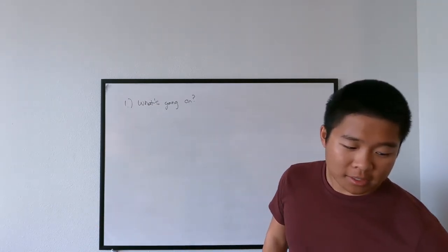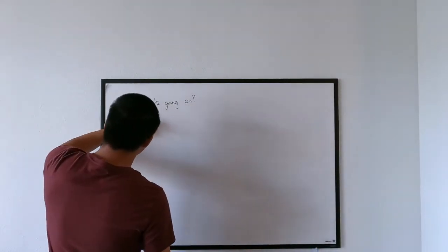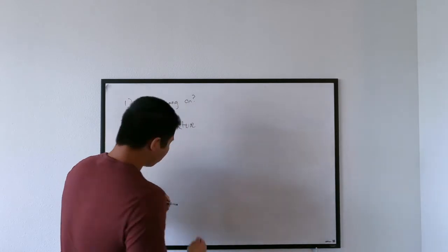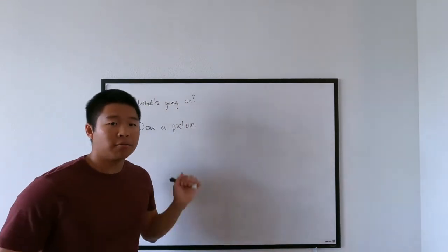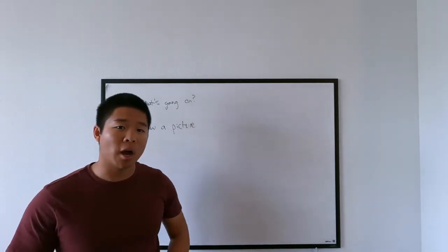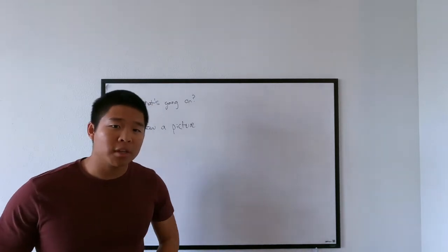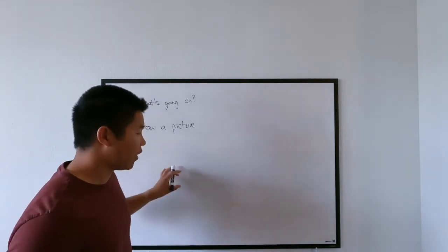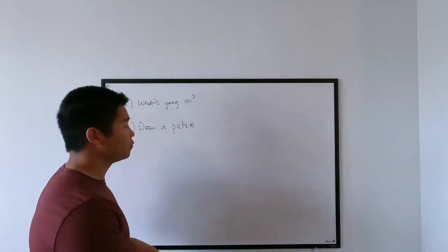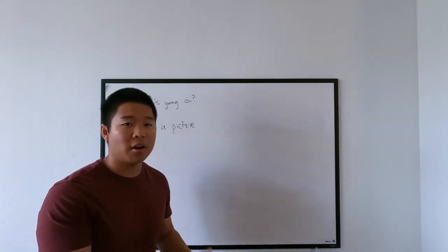So the next step is to draw a picture. Okay? And the reason why I tell folks to draw a picture, especially in this class, is because the systems tend to get a little bit more complicated than they were in statics or physics 1. So while you were able to get away with using the picture provided in those classes, in this class, it's a lot more beneficial to draw yourself a separate picture, right? Simplify it down. Don't leave in all the details, right?